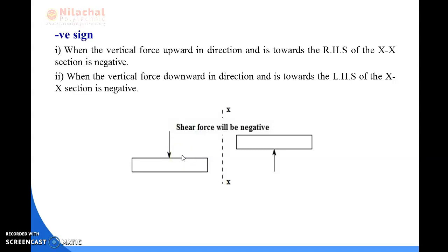You have to remember that when we provide a cut section, if the force at the right side is upward or the force at the left side is downward, then we consider the shear force as negative.